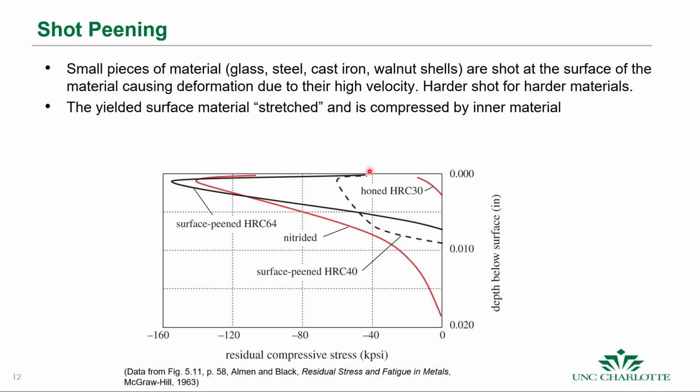But you can see here, these different materials with different hardnesses will have a different benefit from shot peening. So in general, your harder materials can benefit more from this, which is good for us because often we want harder materials because they have a higher ultimate tensile strength. And then we can further improve their life through nitriding, carburizing, or shot peening.